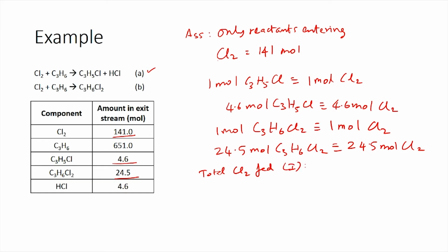So, we can go back to the balance equation which we had, which is input minus output plus generation minus consumption equals accumulation. As the process is at steady state, we will have accumulation to be 0, chlorine is not generated. So, you have only consumption. So, you end up with input equals output plus consumption.